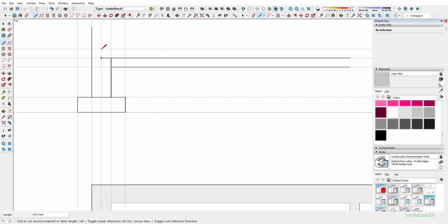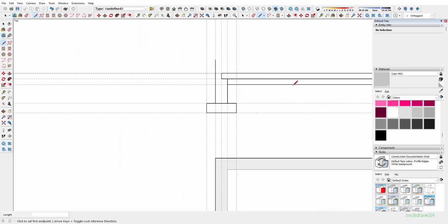And we know it goes one brick layer into the wall, and we're also just going to draw up to there. Obviously, you will draw now the rest of it to the right. I'm just drawing this part to show you what to do here with your projections. Once you've done that above your concrete surface bed, you're going to go and draw in your wall and continue with the window and the doors and whatever you might need on your wall on this side.